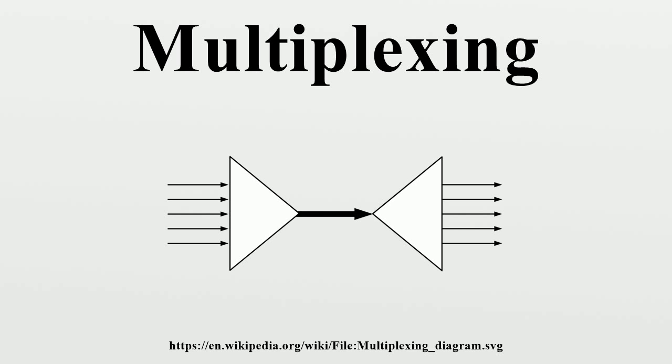Code division multiplexing is a technique in which each channel transmits its bits as a coded channel-specific sequence of pulses. This coded transmission typically is accomplished by transmitting a unique time-dependent series of short pulses, which are placed within chip times within the larger bit time. All channels, each with a different code, can be transmitted on the same fiber and asynchronously demultiplexed.